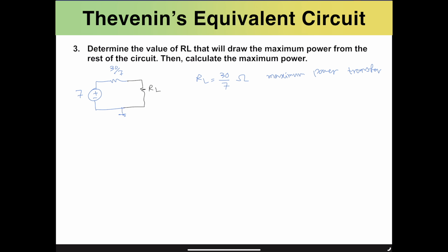So imagine that we are dealing with a voltage source of V. The power that is being delivered to two loads of value RL would be simply V squared divided by 4RL. And that can be calculated by knowing that if this is the voltage source V and we have two resistors RL, the current entering this branch is simply V divided by 2RL.